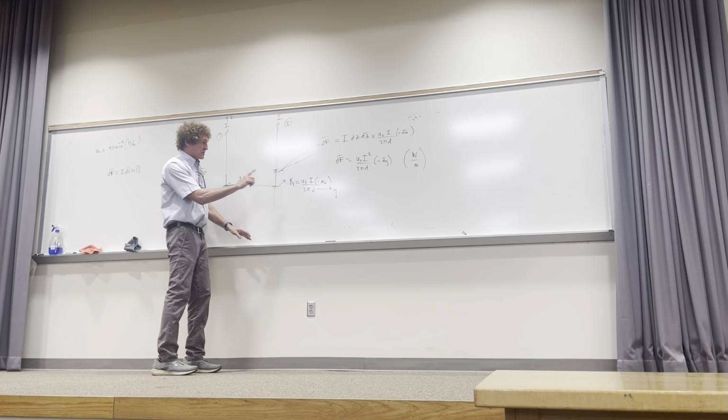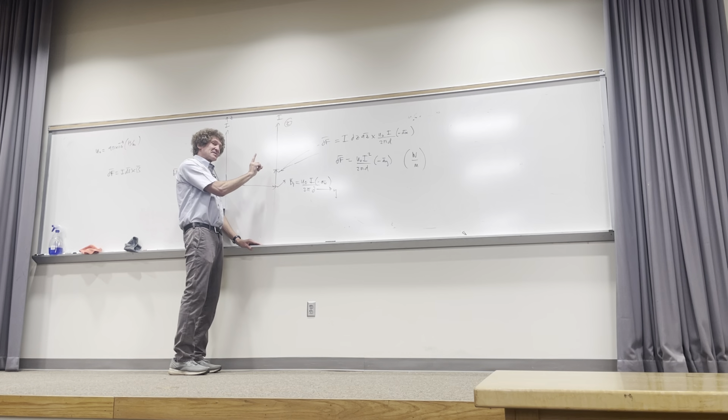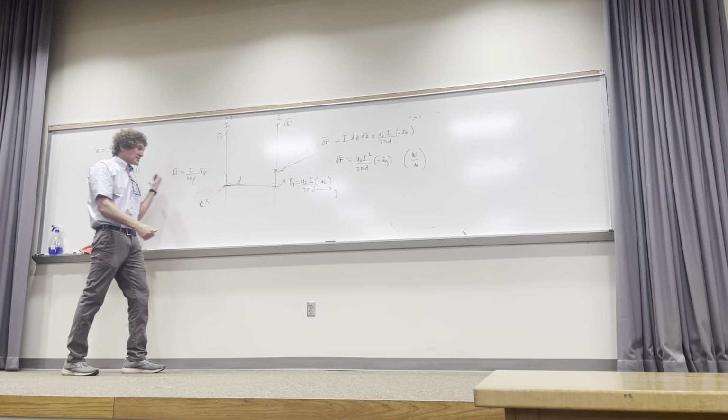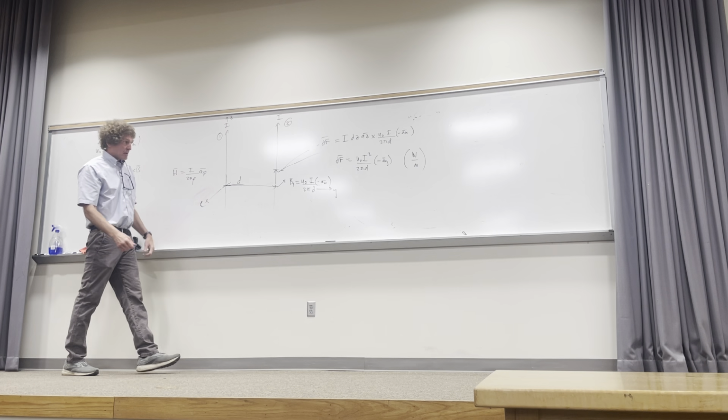Remember, it's always, I want to look at the direction of the force here. I dl is in that direction, right? Cross B, I dl is in this direction. Cross B goes into the board. The force is that way. Can you all follow me? That's minus y, isn't it, class? Take a good look. Right?